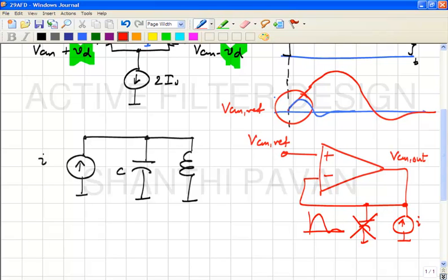So since the feedback loop is not fast enough, a sudden push of current into the output of the amplifier, right, which in the case of an ideal voltage source would result in no step change in the output voltage. In fact, for an ideal voltage source, if you pump in a current, the output voltage will not change. However, this is a, within quotes, fake ideal source, where it's actually being fixed by feedback, but the feedback loop has a finite speed.